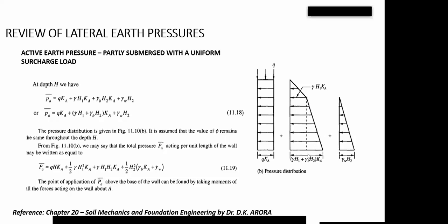Now, you want to explain this other rectangle. This other rectangle simply shows you that the aspect that is not submerged in water keeps on increasing with depth until it gets to the water level. Immediately it gets to the water level, that soil is going to produce the maximum possible pressure, and it is uniform all through the retaining wall. So from the water level, it's going to produce a uniform effect all the way down. The submerged parts from this point will have an effect on the retaining wall that increases with depth, because water is all through from that point to the bottom. I don't know if you get that.